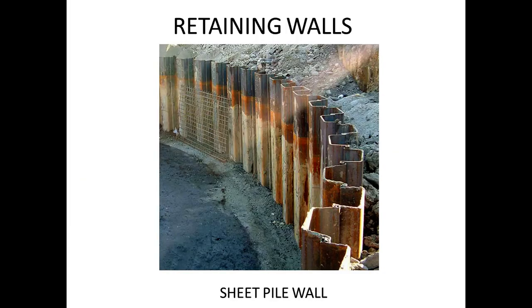Here's another type, again very common. It's called sheet piles, and it's steel. As you can see, steel sections. This crinkliness we'll find over and over again in structure, that this corrugation, this bending or folding of structure, gives stiffness and strength because it's giving depth to the structure. These kinds of walls, rather than cast or poured as the concrete columns we saw earlier, are actually hammered into the ground, so they're also quite useful for water retaining.